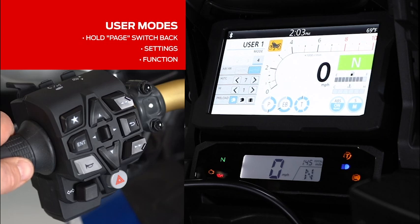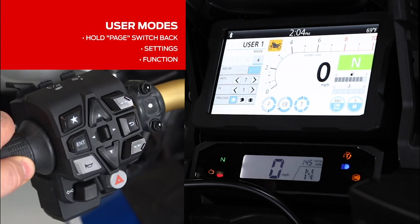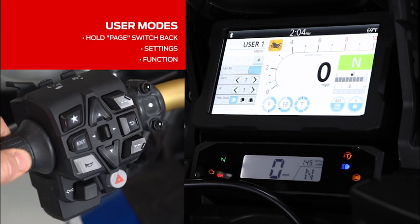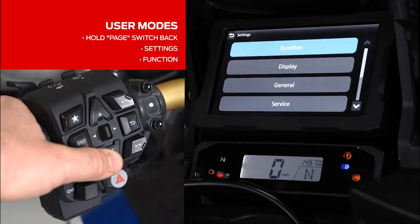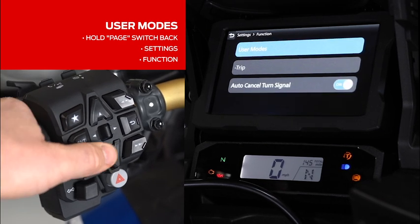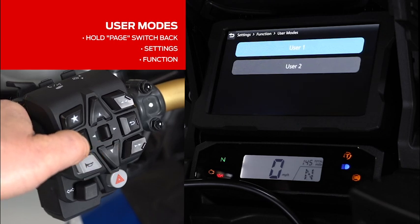In addition to the 4 preset riding modes, you have 2 additional user modes. These are allowed to be customized to your preferences. One thing to remember about these 2 user modes and all the modes is that HSTC and wheelie control adjust independently of the user mode settings. In order to adjust the user modes, simply hold the page button down, go to Settings, select Function, select User Mode.